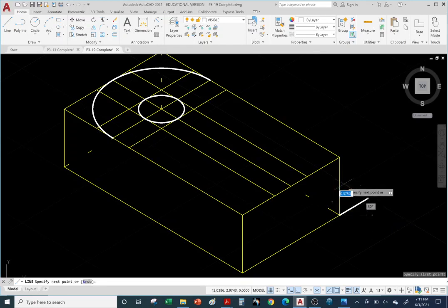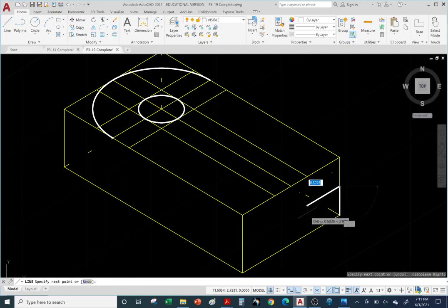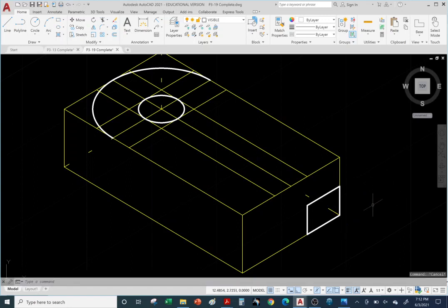Okay, so click. And let me hit F5 so I can go upward. There it is. Or I can just go to the midpoint. So you can see that's 0.375. Click. Then I'm going to go 0.5 inward, 0.5, enter, and 0.375 downward, 0.375, that's half of 0.75, and close it off. There it is. And hit escape to exit.